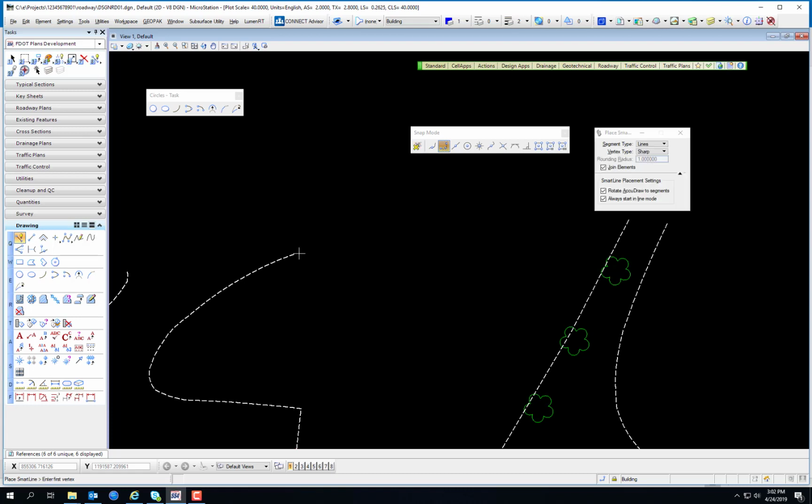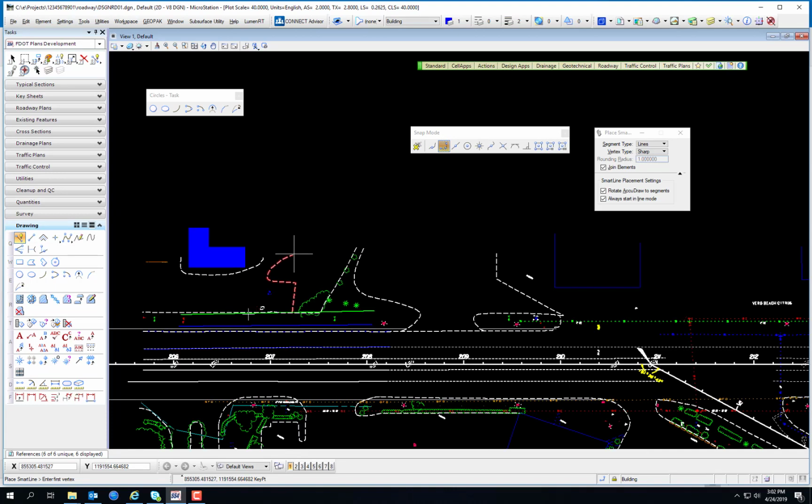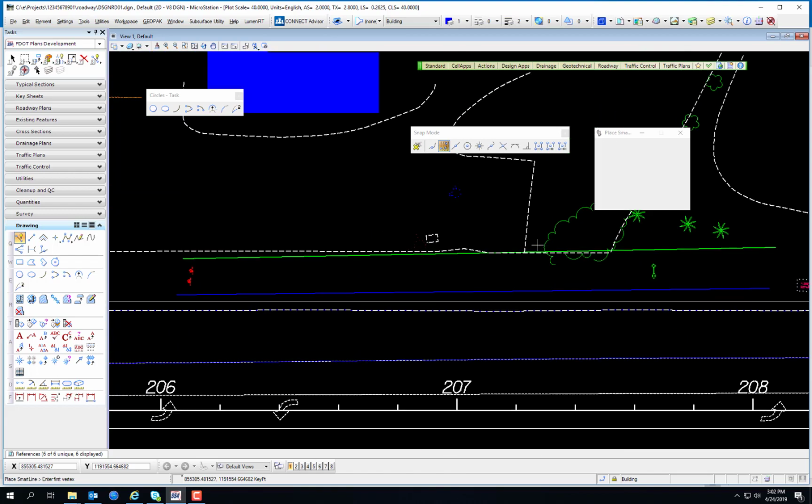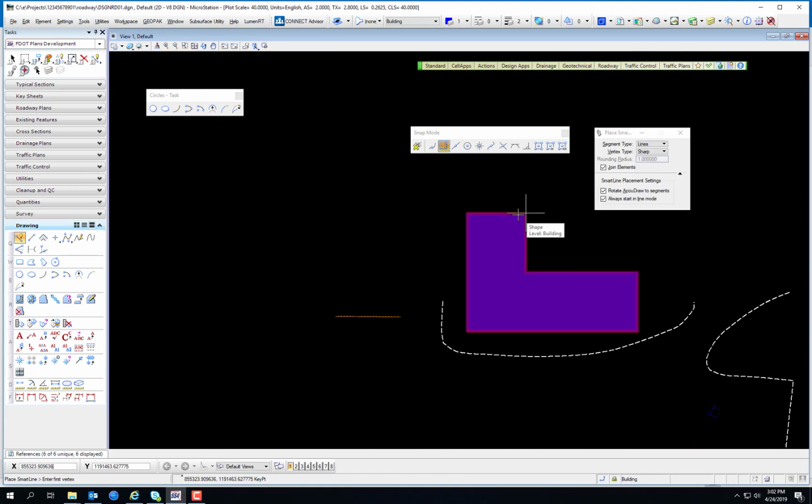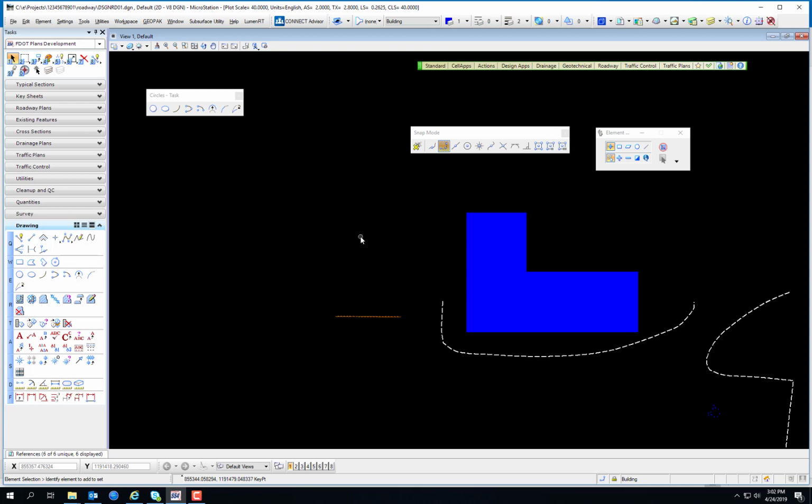If I toggle it off, I'm not getting the tentative hints, and I'm not getting the little yellow X's. But I can still enter a tentative point. Now, right now that's a lot of small lines, so let's demonstrate that on something that's there. So I have key point snap, and those are my tentative points, including the center. AccuSnap works in conjunction with the current snap mode setting as demonstrated, and for the most part is similar in operation to the manual method of tentative snap points, minus the button presses.